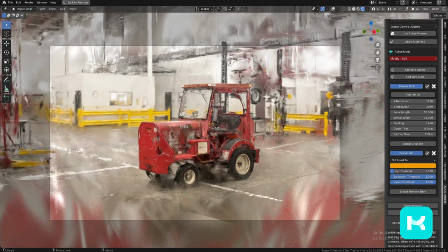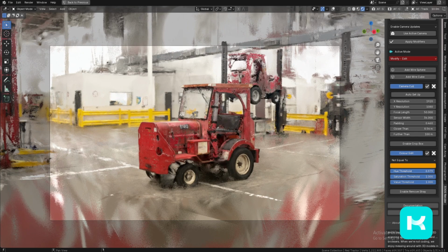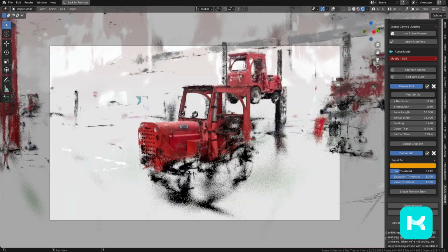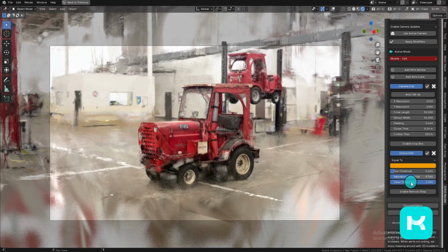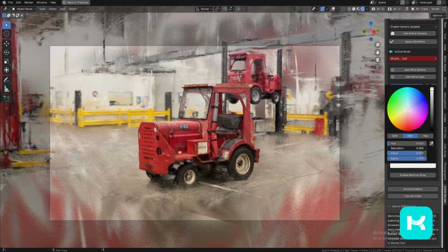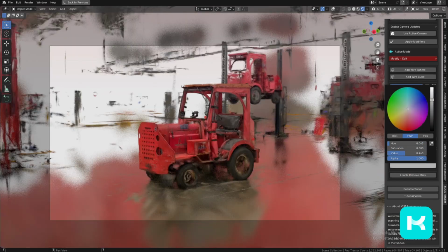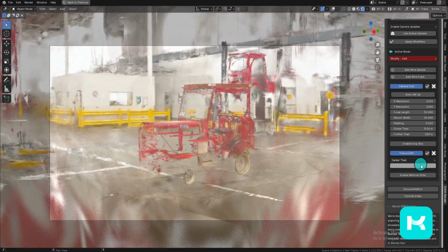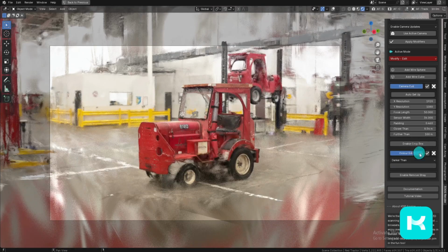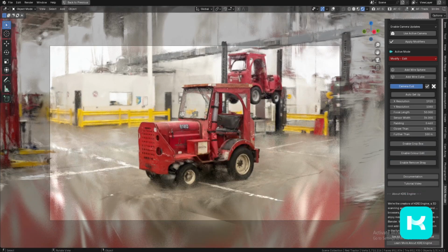Color edit allows you to remove faces according to their color. A color selection and a removal method can be set. Faces can be removed if their color is equal to, not equal to, darker than, or brighter than the selection color. The selection can be controlled with hue, saturation, and value thresholds. However, due to Blender limitation, red values may be very difficult to select.